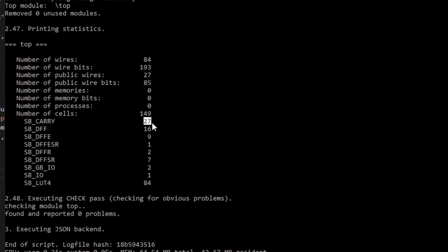Can you do better? Oh, absolutely, because of course, when you do a countdown timer, all you really care about is setting it to the initial value and then waiting until it counts down to 0. You could use something like a linear feedback shift register, and then you wouldn't have any carries. It would certainly be a lot faster. You wouldn't have any addition logic because you're not really doing addition. All you're doing is you're counting in a sort of pseudo-random sequence.